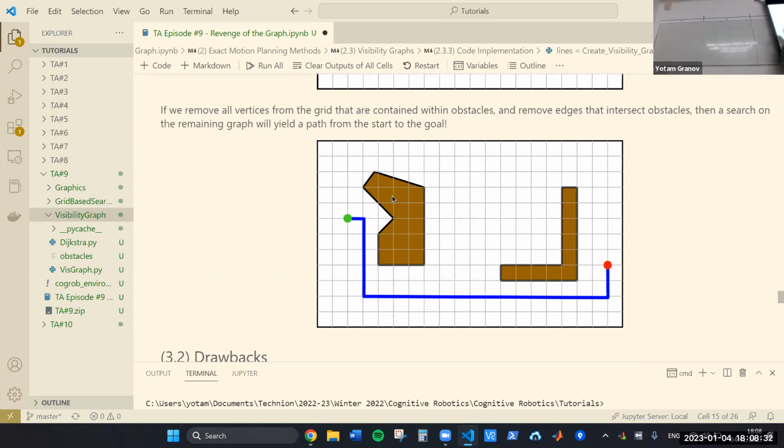You can already see that this again isn't optimal. Already here, we didn't find an optimal path, because we could have definitely gotten closer. This is because we discretized the space and we've limited ourselves to move in 4 directions. We only go up, down, left, right. Of course, we can add more freedom, so we can go 45 degrees each direction. We can do 8 direction planning. Of course, you can imagine that the more directions we add, the more complexity there is in our algorithm. So we can't just have it go to any angle, because that would definitely increase the complexity of our algorithm.